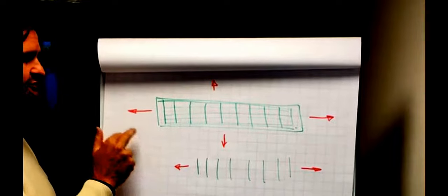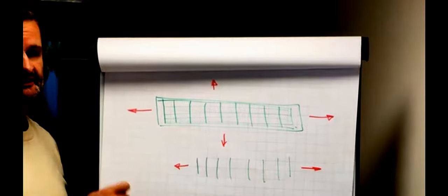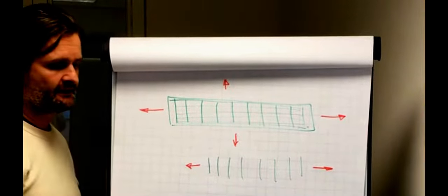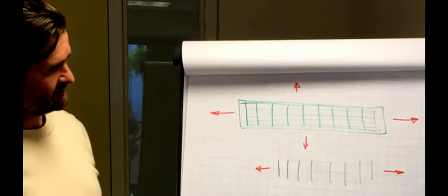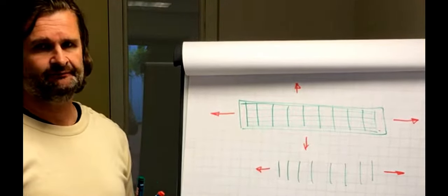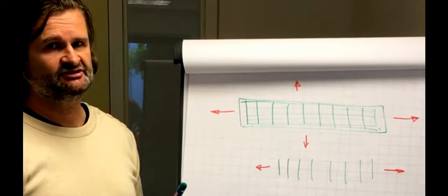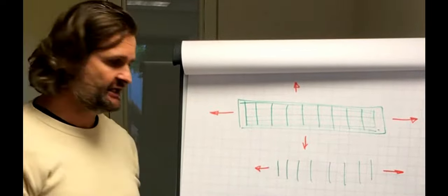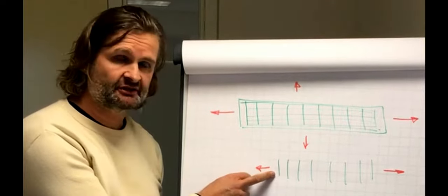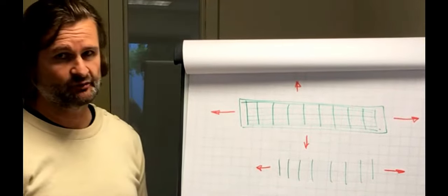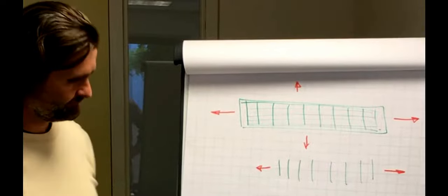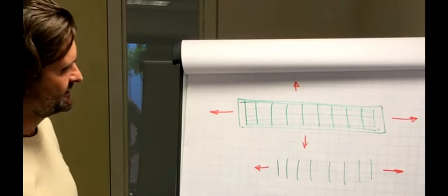That deformation is not high because the fibers take a load, but it is still there. And contrary to what you might think, glass fiber is very flexible. A glass fiber composite is even 10 times more flexible than steel. That means for any given load that the deformation is also 10 times more than you would expect for a steel pipe. And that gives the following effect.